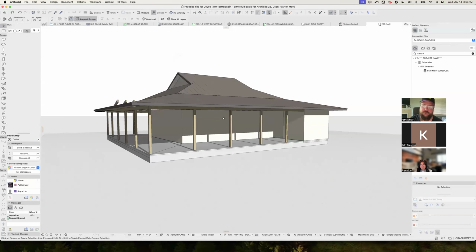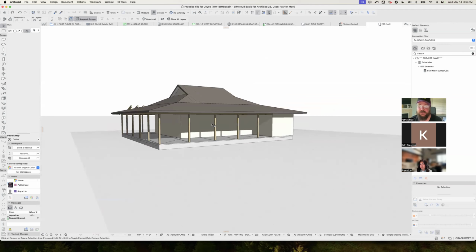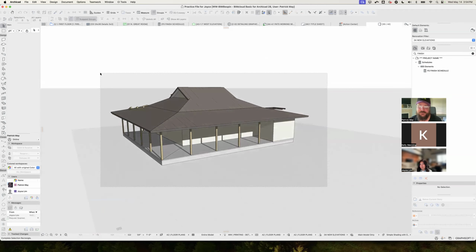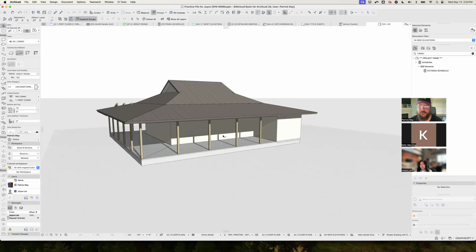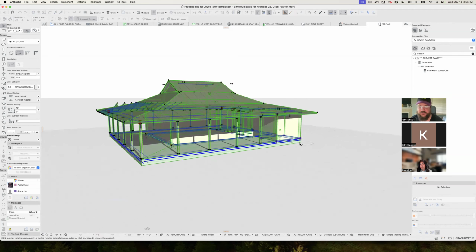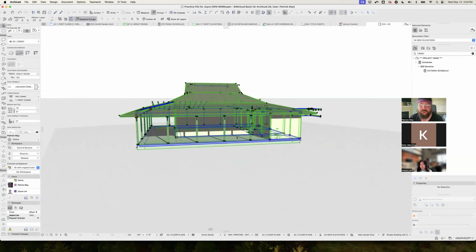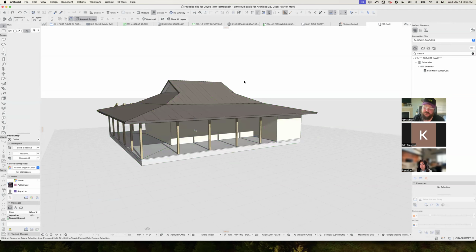We also have options in Twinmotion. So if you were actually doing a sun study for a client, we would be doing that in Twinmotion. But because you're not actually designing or adjusting the building in Twinmotion, it's not necessarily the most helpful. You don't get that immediate feedback. If, for example, I knew that I needed to block this sun at the winter solstice, you can physically rotate the building and see an immediate effect of what that sun's doing with that building rotation live in ArchiCAD, provided that that project location setting is set correctly.